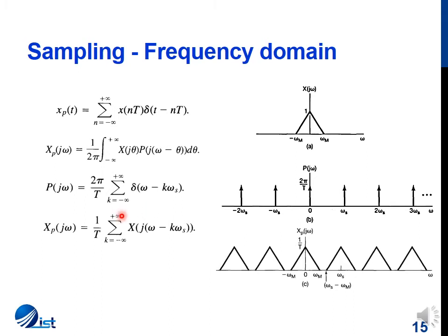So if we convolve the signal by this impulse train, we'll get a train of signals occurring simultaneously. So let's see what happened with the frequency spectrum. Say that our signal X of j omega was band limited such that the maximum frequency it possessed was omega m. This is our impulse train, which is sampled at a frequency omega s.